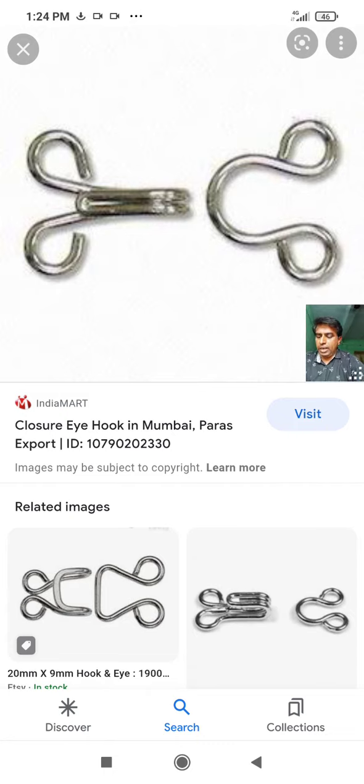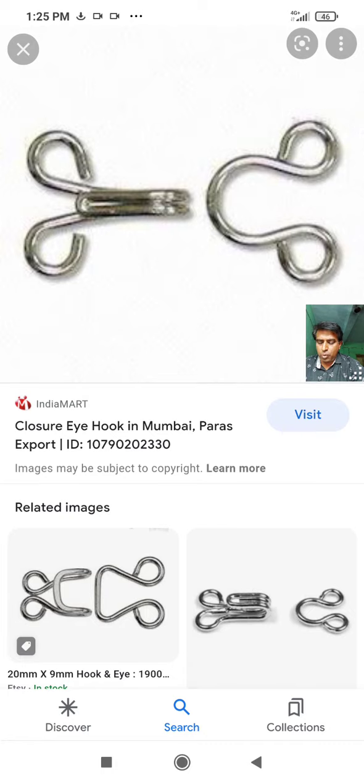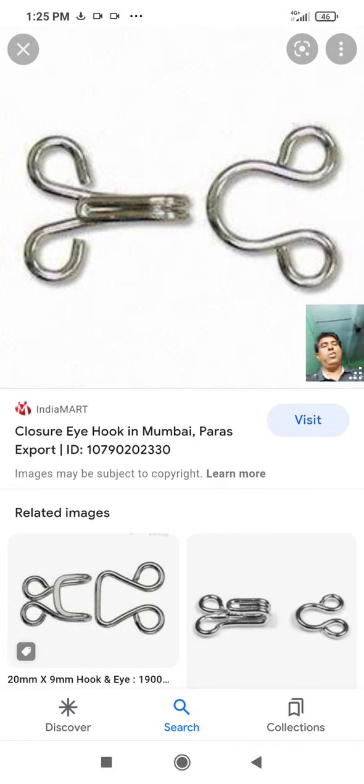So mislocated or poorly attached closures will subject the zipper teeth to very high stresses at the top. Garments that are sized small or retail customers that purchase undersized items promote failure because these closures are usually left open and the slider is used to keep the opening closed. So I will leave that to you. So this is hook and eye closure. Next one is waistband.